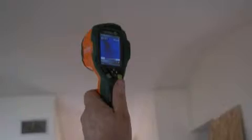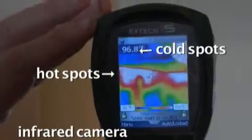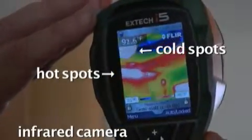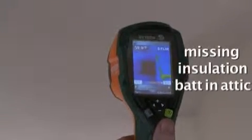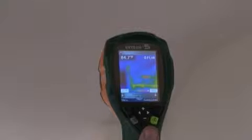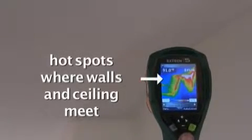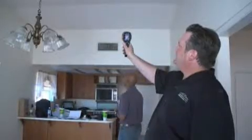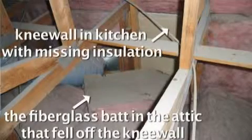The very best way to identify air infiltration paths is to use our infrared camera. We slightly depressurize the building using a blower door, exhausting air from the house, and we do that for several minutes when we have at least 15 degrees Fahrenheit temperature difference between inside and outside. Once we run the blower door for 15 minutes, we're able to see the air leaks even if they're inside a wall with our infrared camera.